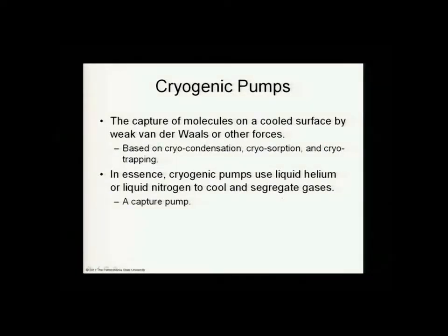Cryogenic pumps. This is literally the water glass kind of idea. Well, not literally, because the coolant is generally helium, liquid helium. But we're capturing molecules on a cooled surface, just like you can capture water vapor on a cold glass of water, the outer surface. Here we're going to capture molecules on a cooled surface by weak van der Waals forces or other types of forces.